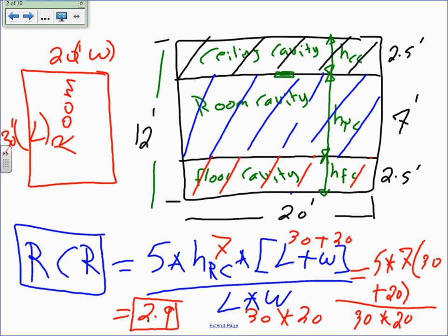It goes from 0 all the way up to 10 feet in this case. So my floor cavity ratio could be 0, because I want the light to be right at the floor. If I want the light to be right at 2.5, then I have to calculate my room cavity ratio, basically 2.5 all the way up to the ceiling. Any question, guys, about this?